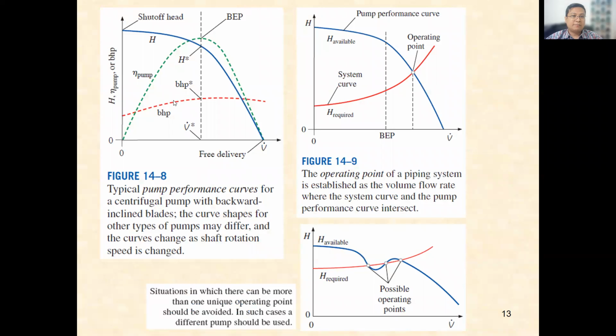Okay, this one, as I mentioned before, shut off head is when the head is higher, and then no delivery. And then when the head is zero, delivery will be higher, as I mentioned before. So when head is zero, it is easy to transfer the liquid.